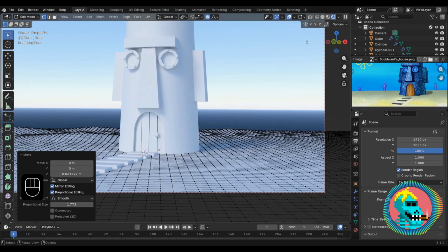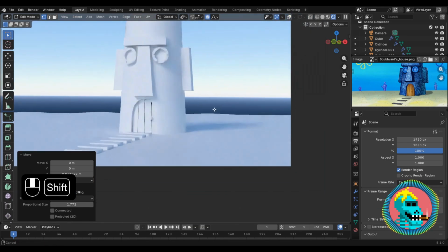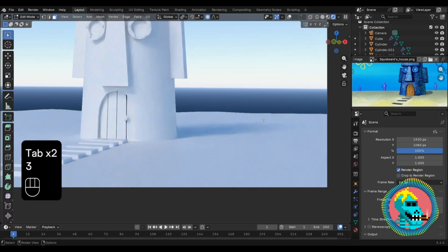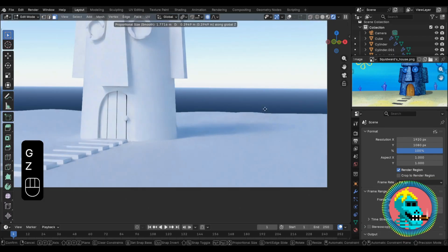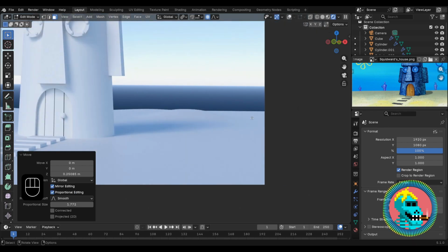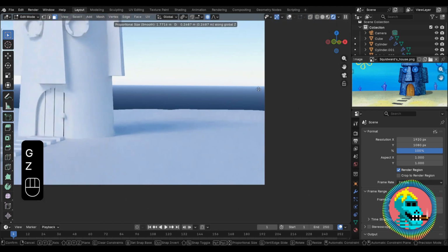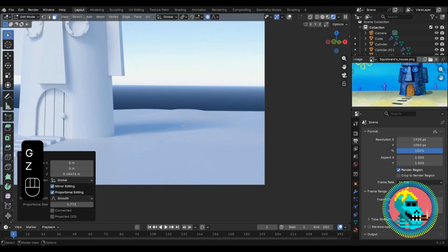Also, to better see what is happening, we can turn off the display of points. At the same time, edit mode is enabled. It's working, so we're kind of working blind. Sometimes this is useful in order to see the final result, which is sometimes overlapped by faces and edges.